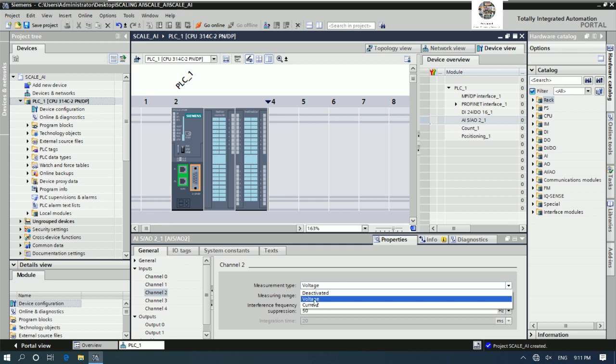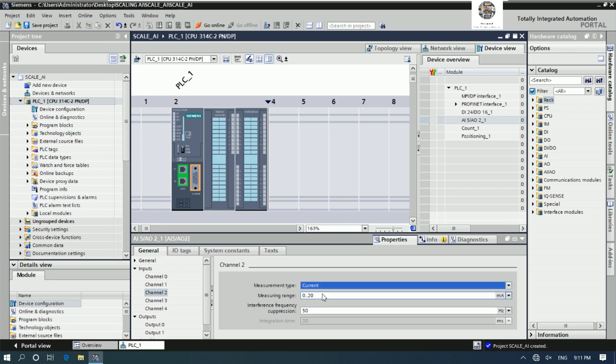If anyone has a volt signal, use the volt input. For example, the VFD uses volt, so we can select volt here, and wire the connection following my drawing.